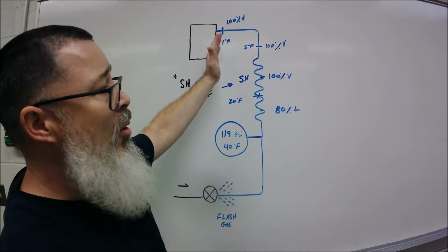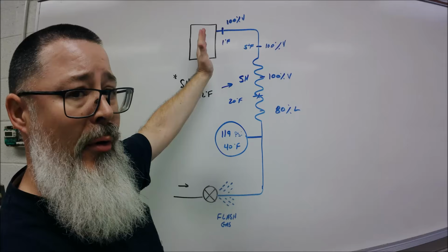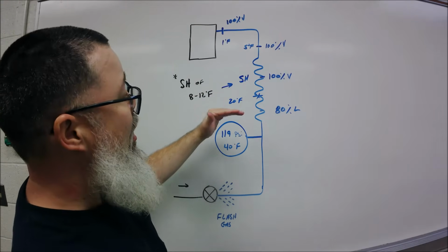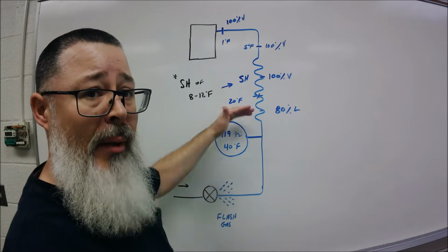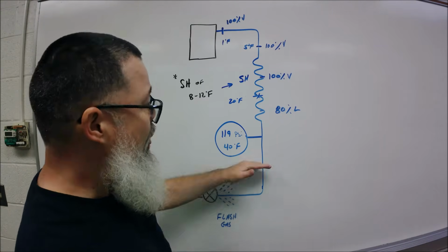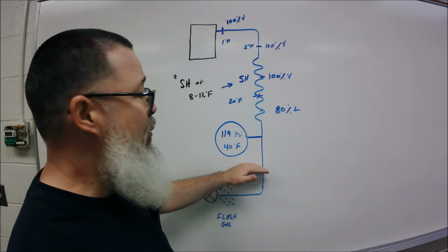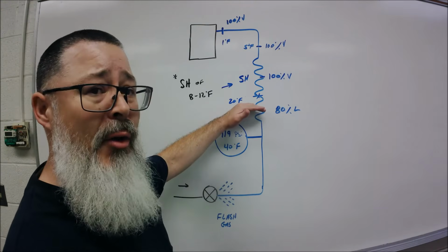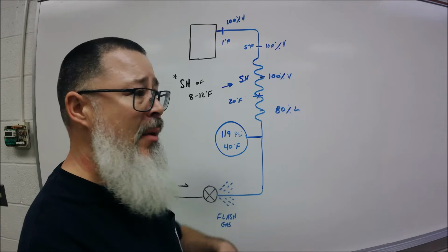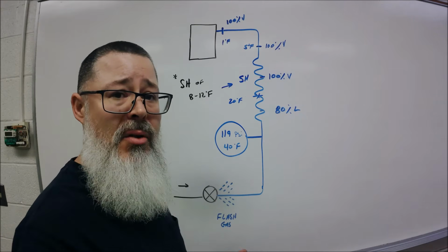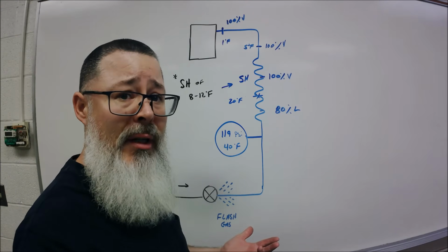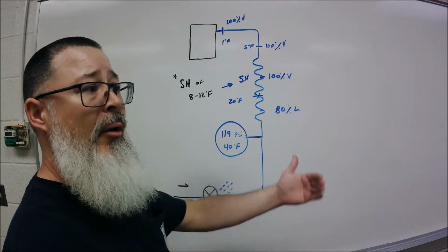The more you have, the further back from the compressor it actually happened, which means the sooner that my liquid went away. If you have an undercharge of refrigerant, you don't have enough refrigerant going very far in your coil to do any good, okay? What you do have is going to quickly be hit with heat, and it's going to change into a 100% vapor, and then it's pretty much done moving heat. It has to be cycled back around and through.